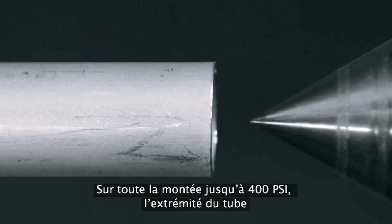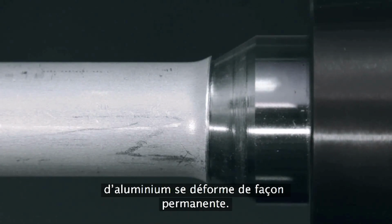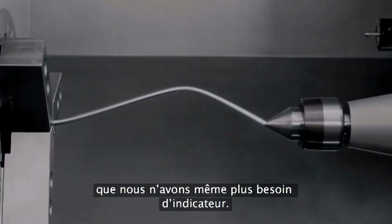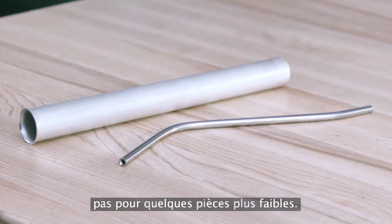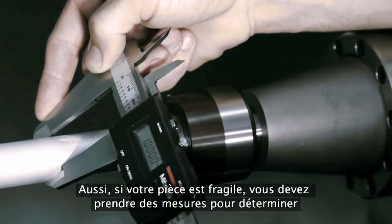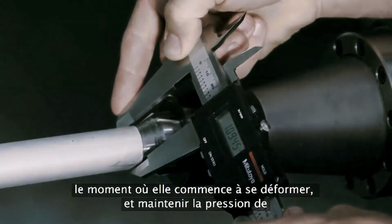All the way up to 400 psi, the end of the aluminum tube permanently deforms. Meanwhile, at 400 psi, the steel rod bends so much we don't need an indicator anymore. Okay, so why did we show you this? We want you to realize that 200 psi will probably not work for some weaker parts. The point is, when your part is fragile, take some measurements to find where it starts to deform and keep your tailstock pressure below this point.